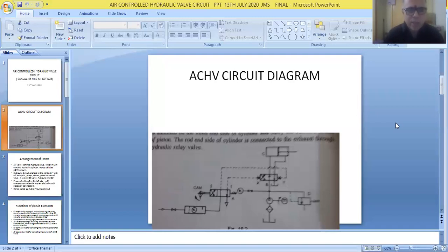So just like the hydraulic DC valve, this valve will also have 2 positions. In the first position, the inlet will be in contact with the first outlet, and the second outlet will be in contact with the exhaust port of the air valve. Therefore, air will enter from the left hand side of the DC valve and leave from the right hand side of the hydraulic DC valve.